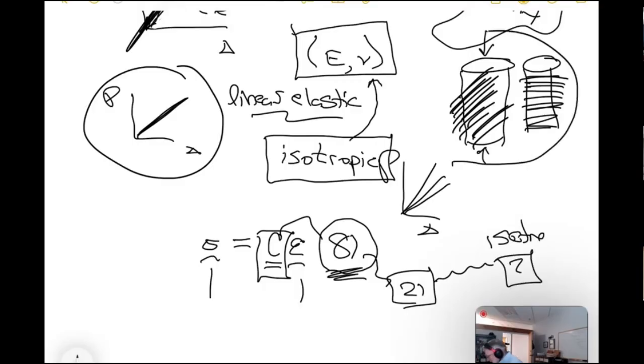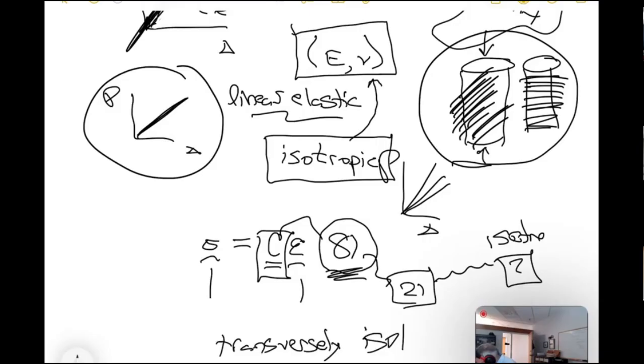And so like this sucker here, that would be something they call transversely isotropic. And I can't remember, it's either 5 or 6 elastic constants for that. So you would have to do tests in different orientations of this to back out these elastic constants.